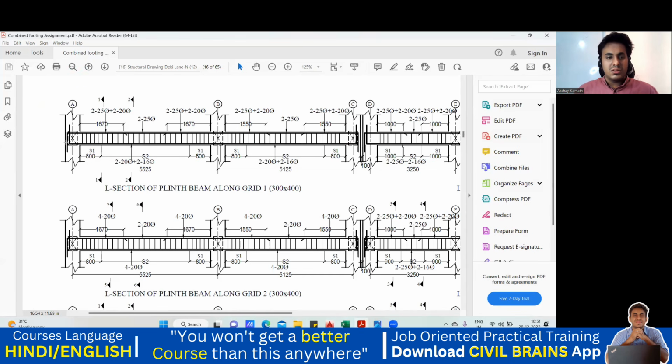See, this is one bar, this is your top bar. Then comes your bottom bar, you can see here. Here comes your bottom bar. Then you get a top left extra, something like this. You can see this one bar here, this is my top left extra. Then I get my top right extra bar. And then I get the middle straight bar. So this is a middle straight bar, right? And what the different diameters are, everything is mentioned here, and the stirrup is also mentioned.